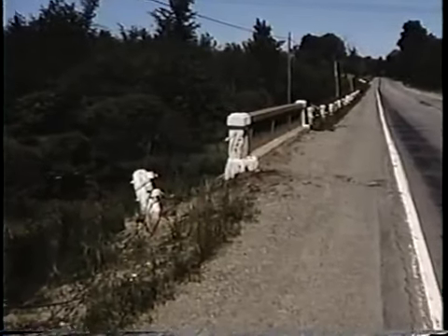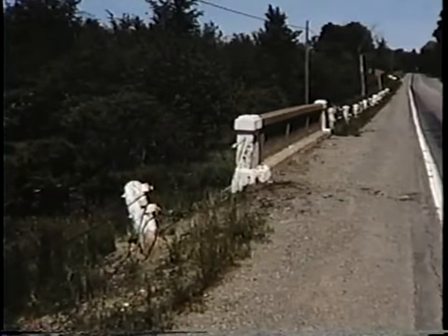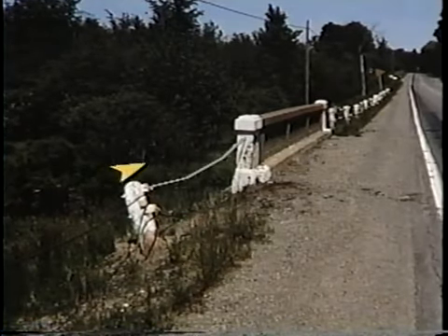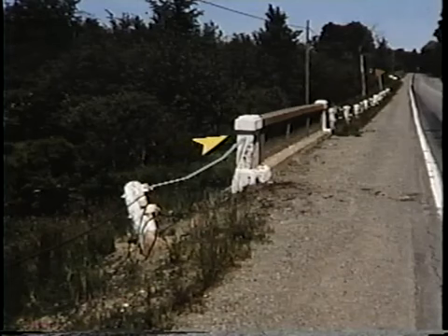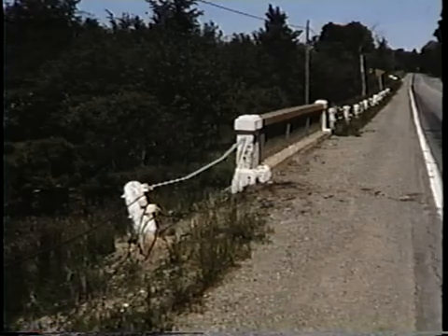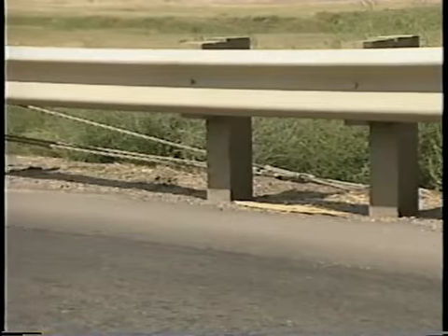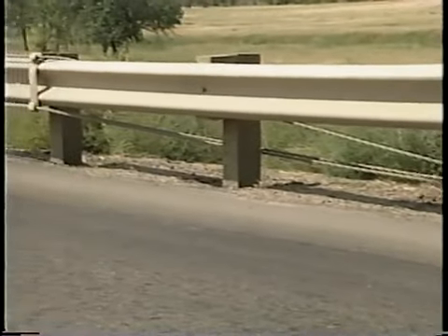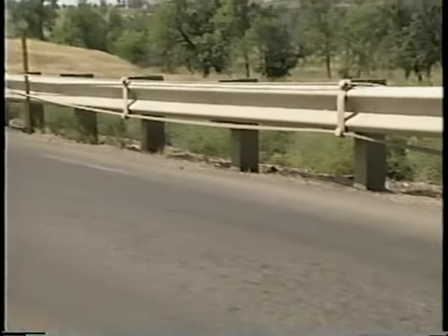This cable guardrail transition to a bridge rail is unsafe because it would redirect the vehicle into the rigid end of the bridge. When two longitudinal barriers with different stiffnesses are joined, there must be a smooth transition to avoid pocketing accidents. A transition between a 3-cable guardrail and a W-beam guardrail was developed to solve this problem.